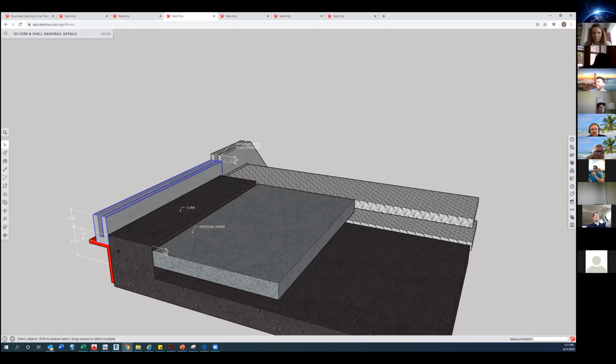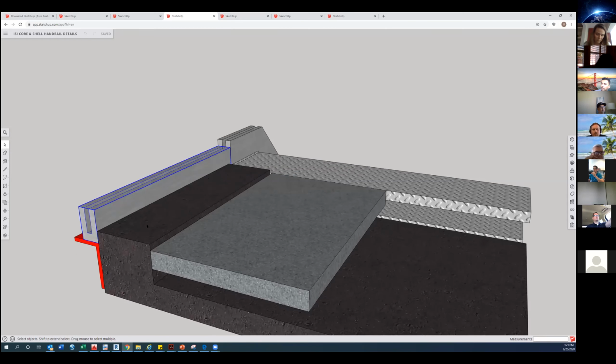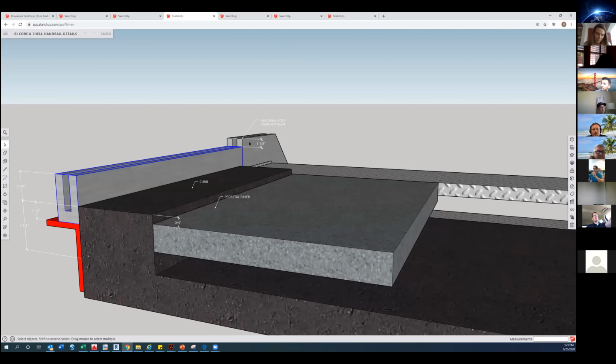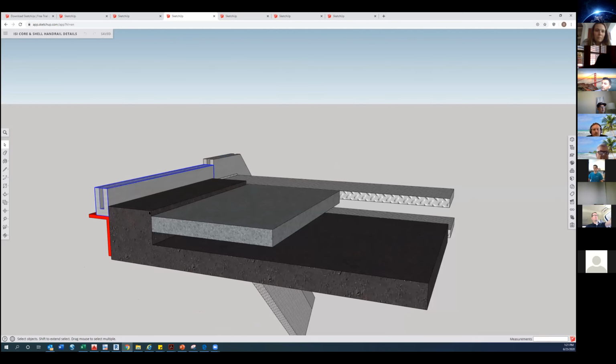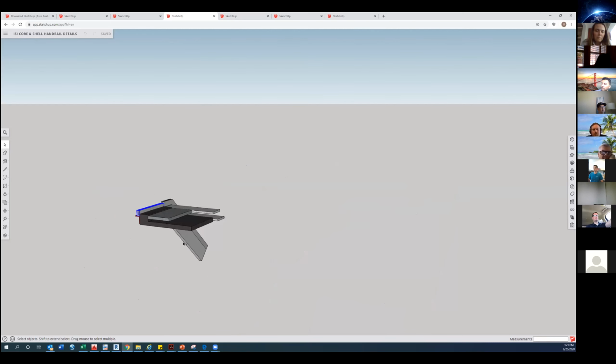So I detailed everything. I said you have the stair stringer, which is finished floor. The top of this paver is finished floor. You have this curve that's 3/4 inches too tall. This is the step that you see. It's about an inch or an inch and an eighth. And then I said, okay, this is what needs to happen. So I made that, then I copied it.